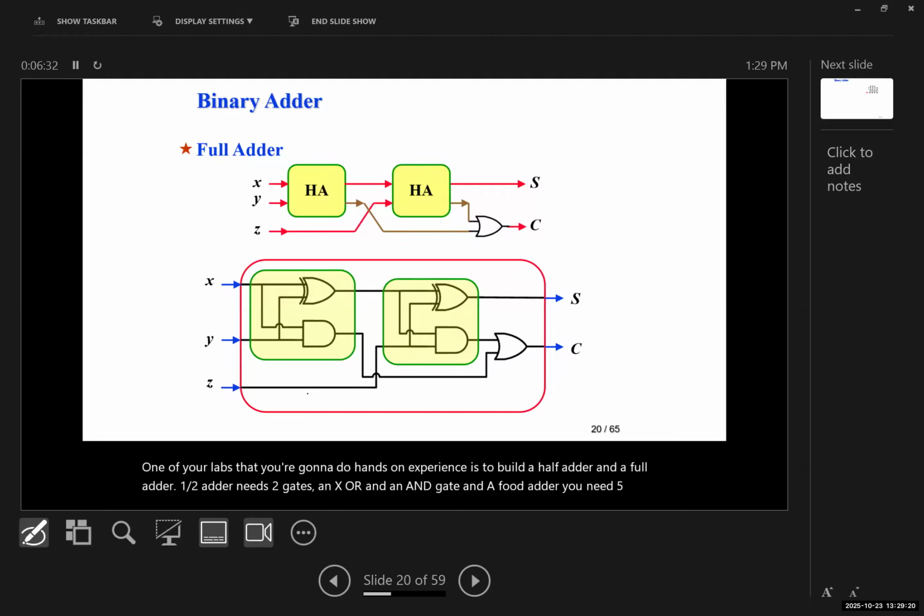The logic diagram inputs are P2, G2, P1, G1, P0, G0, and C0. And the outputs give us C1, C2, and C3. What this does is first calculate all the carries and at the same time add all the numbers. So at the end, you're going to just have everything. Again, as mentioned, it's a look ahead carry, so it calculates the carries before it adds the numbers, or at the same time.